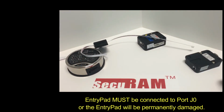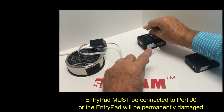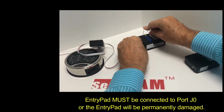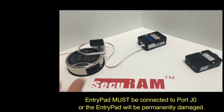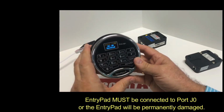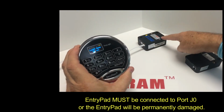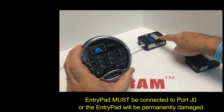So with the cable connected, we now use the reset hole. We press 1, 2, 3, continue to press down and hold, and now we plug in our lock cable that's coming from the junction box. And you can hear with the spring bolt lock, the motor actually cycles when you plug it in. Count for 5, 1, 2, 3, 4, 5, and release. Now, we enter our supercode. It's going to verify and say, which lock do you want to open? We're going to say lock number 2. And lock number 2 now opens. In opening this lock, it has named this lock, lock number 2.